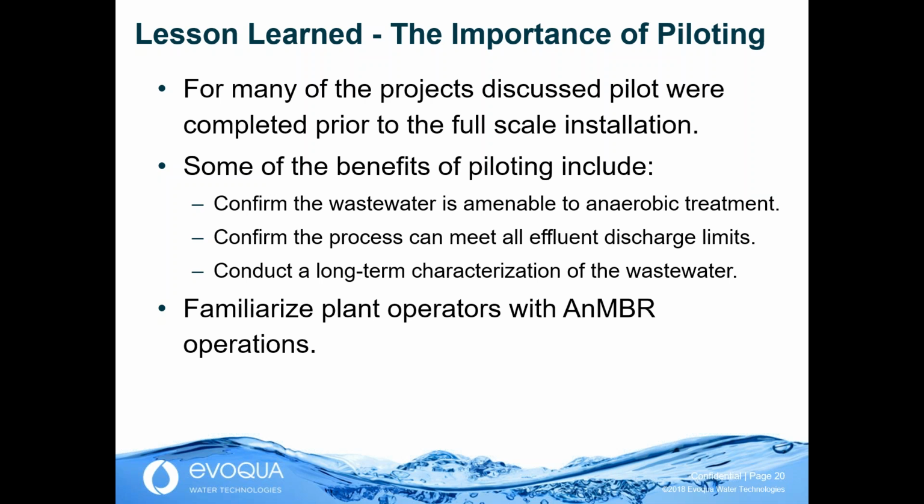Now I'm going to talk about some of the lessons we've learned through these systems. The first one I'm going to talk about is the importance of pilots. For many of the projects that I discussed earlier today, pilots were completed before we started them. Since an anaerobic MBR is a newer technology, we don't have experience with treating all kinds of different types of wastewater, so you don't know what things we're going to run into or what complications. So often we've done pilot studies on a lot of these full-scale systems to make sure the membranes are going to work. Through pilots, we make sure that the wastewater is amenable to anaerobic treatment.